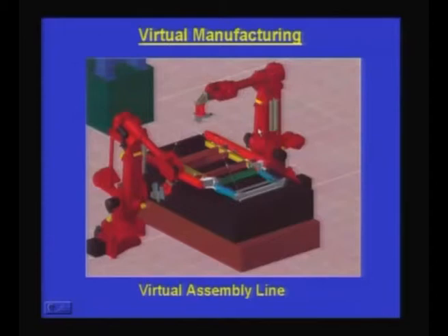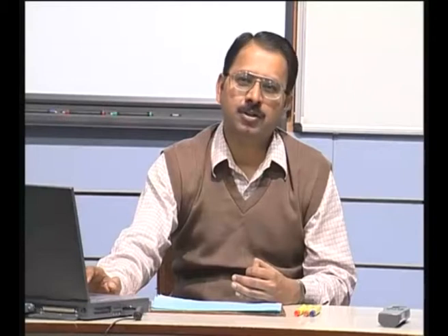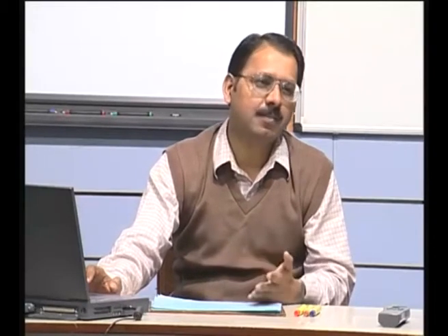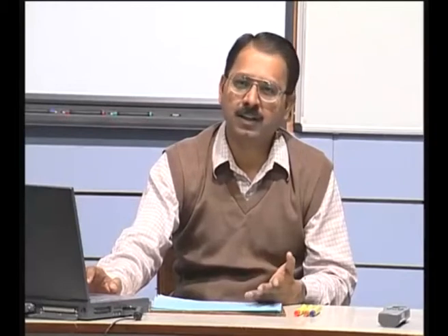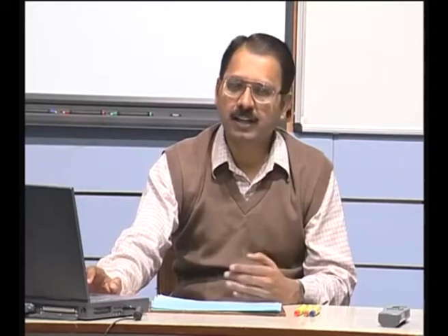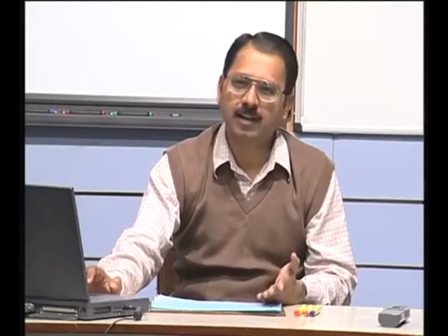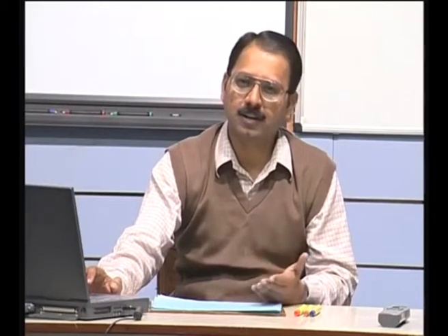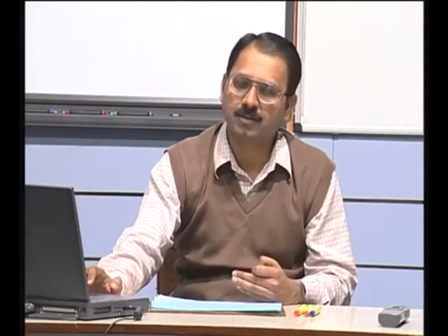This kind of virtual manufacturing helps to answer questions called what-if scenarios. What if this happens, or what if I remove one of the welding robots, am I still able to do the entire fabrication in the desired time, or how much extra time is required if I use 6 robots or 7 robots to carry out the welding process.